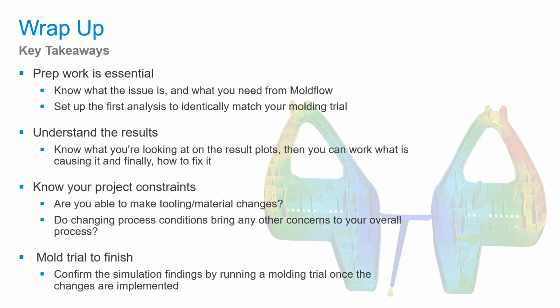And then finally, leading into an actual molding trial, for the simulation to actually be validated, we want to actually test it within the mold. Again, it will be a little bit more difficult and time consuming if you do have to make those tooling changes or even material changes, because sometimes materials do require some tooling adjustments such as draft or shrinkage.